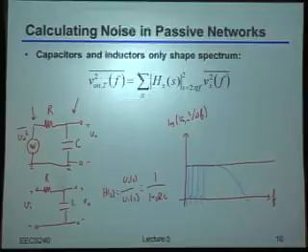Now, by the way, this also tells you, if you were interested not just in the noise density or the spectral characteristics of the noise, but you actually wanted to know at the end of the day how many millivolts of sigma variation you really have, this tells you exactly the way you do it. Because what you'd do is take that transfer function and integrate it across all of these different frequencies to find the total area under the curve. That's exactly what would tell you the net noise variance in this case. Does this make sense to everybody?